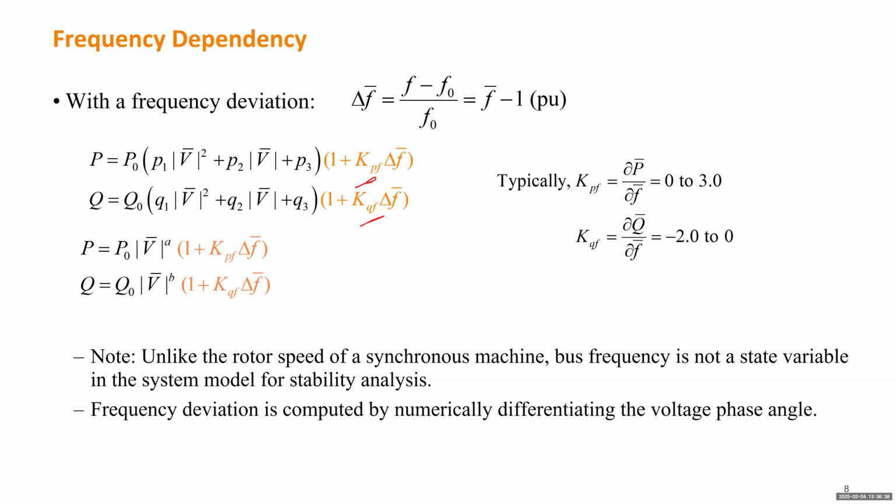The voltage phase angle is a function of time, because under steady state we usually use power flow to calculate a single number for the angle, but how do we get that function? If you measure three phases, you have data in the A, B, C frame, and you do the park transformation, which gives you D and Q. From D and Q, it tells you the angle. That's similar to how we estimate the delta for a generator.